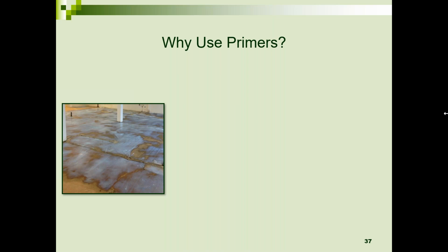An important part of a self-leveling installation is the primer application. Once the surface has been cleaned, you're ready to go. What we're looking at here are one of possibly two problems. When the primer was applied, it was not applied evenly. The contractor skipped some spots, and we can see that where the concrete is still showing through the surface, or the concrete was so absorbent at those points that the primer was applied and immediately sucked in. And those are the two issues. You want a uniform film over the entire surface, not this random here, there, here, there. You're going to have problems.